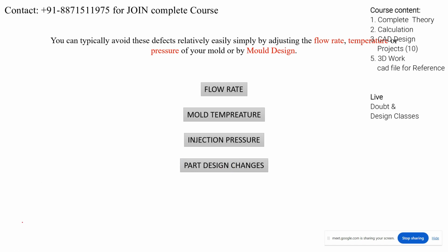Is it clear? So by adjusting points like flow rate, molding temperature, injection pressure, or the part design change, or the mold design work, which is the last one, which may go into a revision.